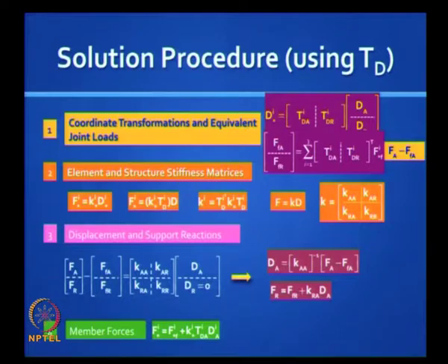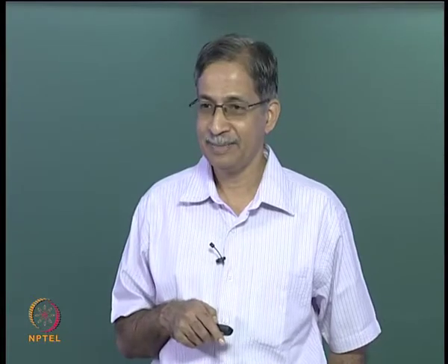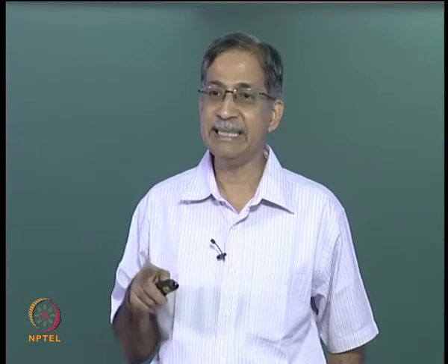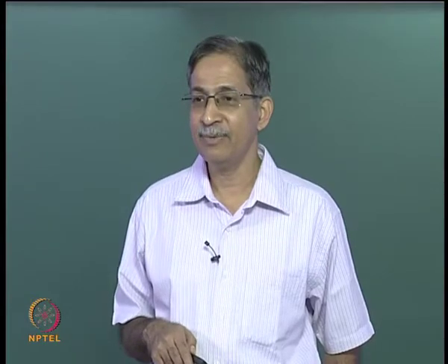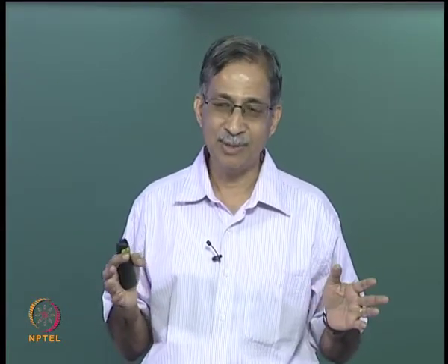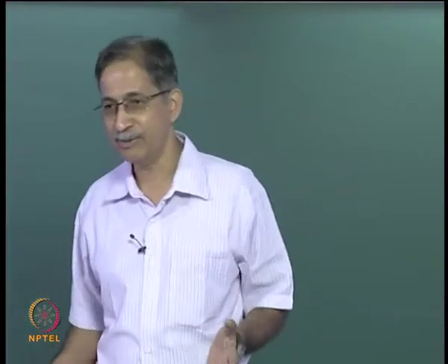any support settlements. Also we are going to use a slightly different technique of generating the stiffness matrix and the fixed end force vector. We will use the TD instead of the TI. I want you to recall the difference between using TD and TI. TD is a displacement transformation matrix. It has the big advantage of you not worrying about the slotting, but it has a disadvantage in terms of storage and programming. You will have to deal with larger matrices, but for problems like this it does not make too much of a difference.